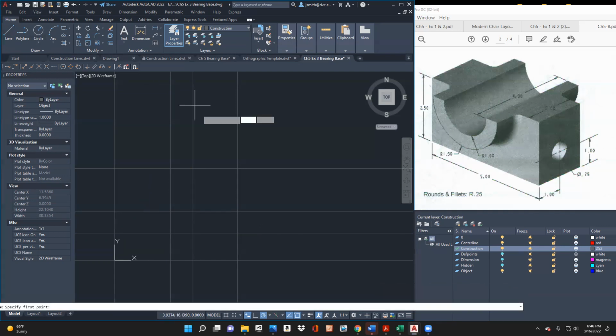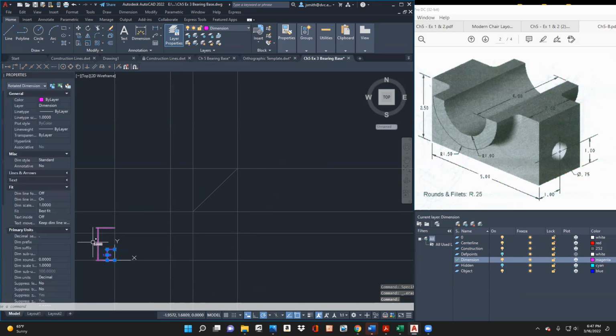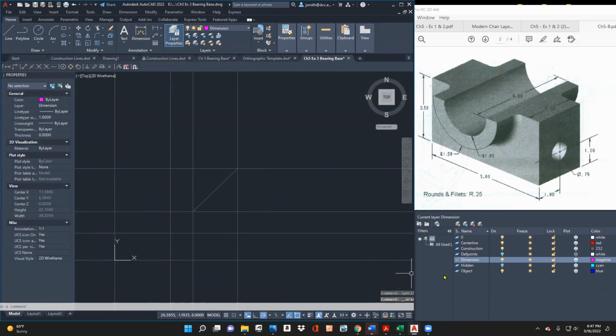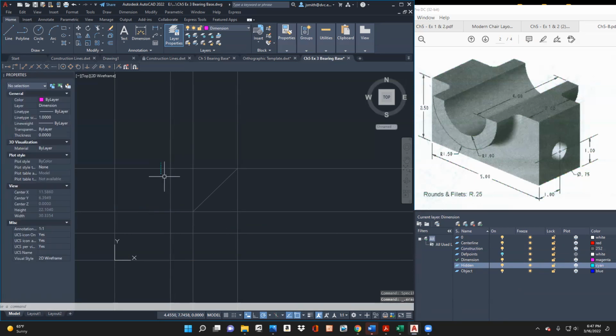All right, so I should be able to take a line here. This is going to be 45 degree. And it's probably not a bad idea, before I get too involved here, to turn on my dimensioning, make that my center line. And I need to turn it off from before. I didn't have it off before, so let's turn these off. All right, so now I probably have those hidden lines on too. Let's just get rid of those. So the lesson here is when you save it from another one, turn all the layers off and then delete it. All right, so we're good here.